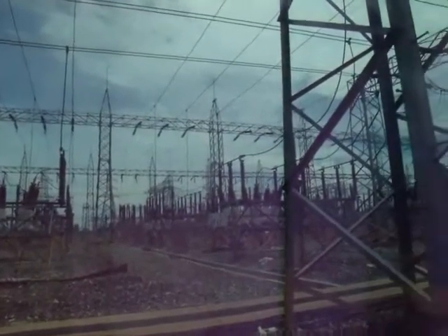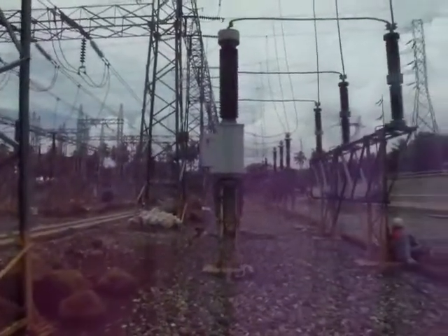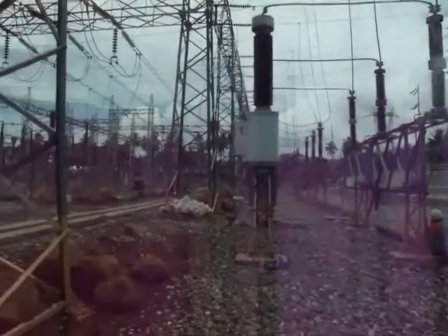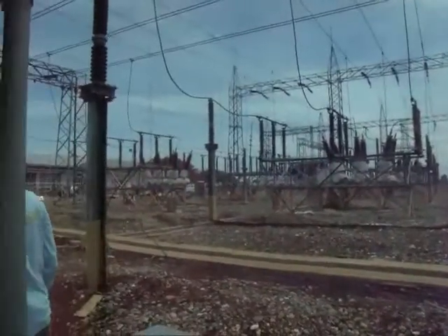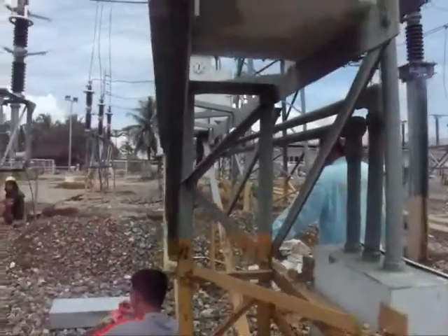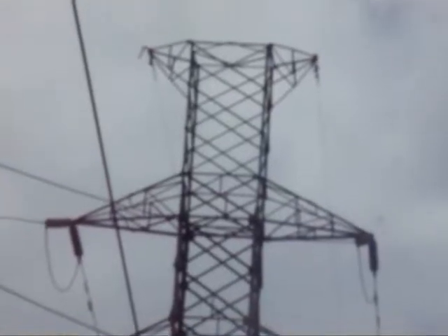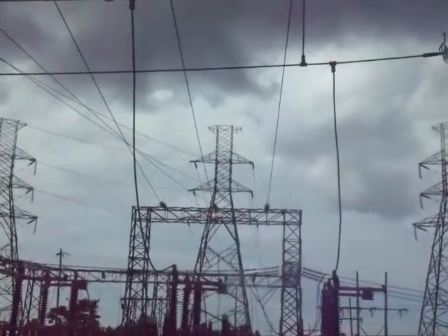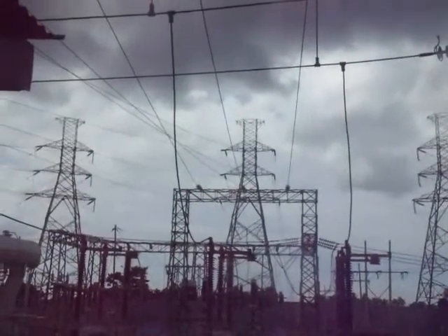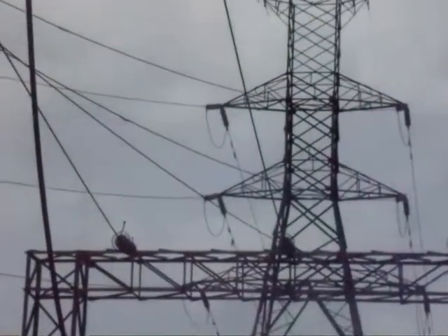Transmission lines also interconnect neighboring utilities, which permits not only economic dispatch of power within regions during normal conditions, but also the transfer of power between regions during emergencies. High voltage transmission lines are terminated in substations, which are called high voltage substations, receiving substations, or primary substations. The function of some substations is switching circuits in and out of service. They are referred to as switching stations.